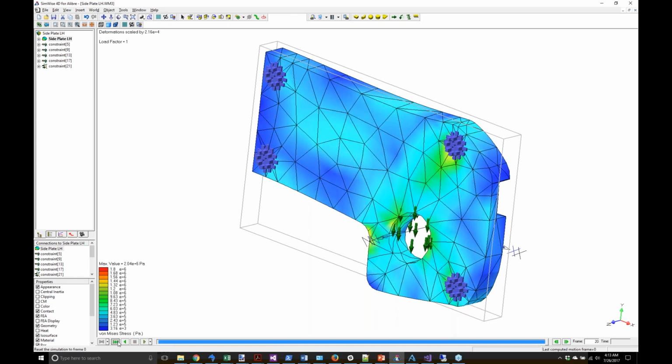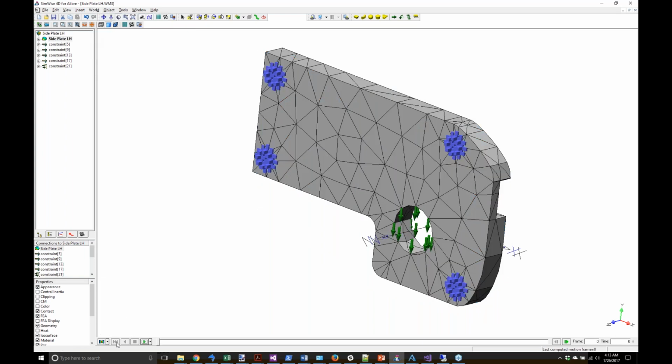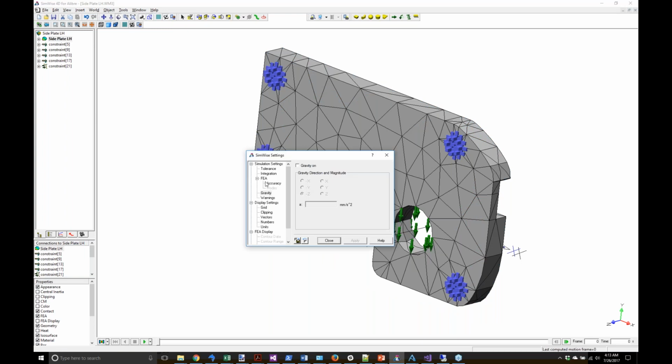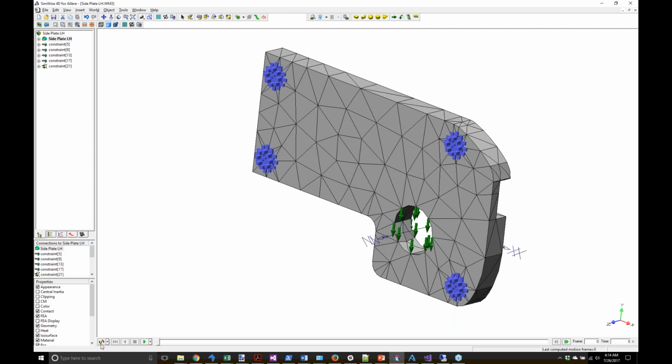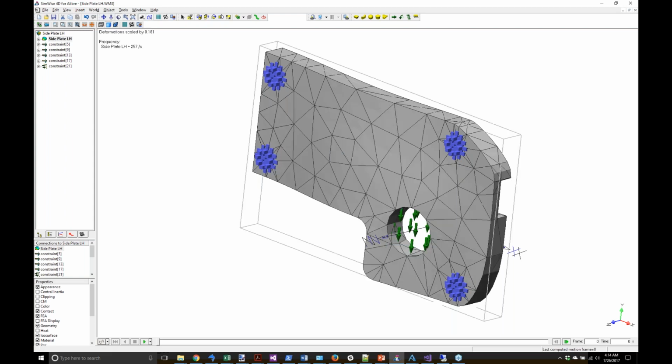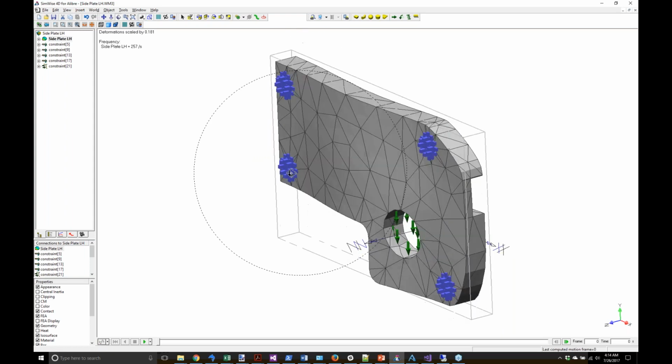So this was a stress analysis. Let's ask the system to do natural frequency analysis, but first let's say we'd like to calculate 8 modes at this part. So we just click that button, and there we go.